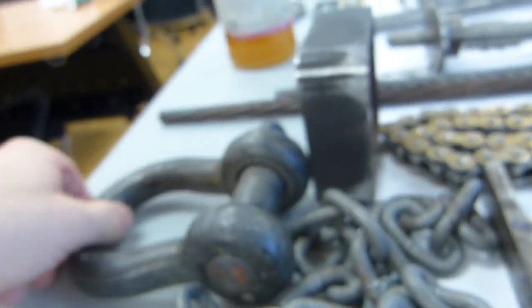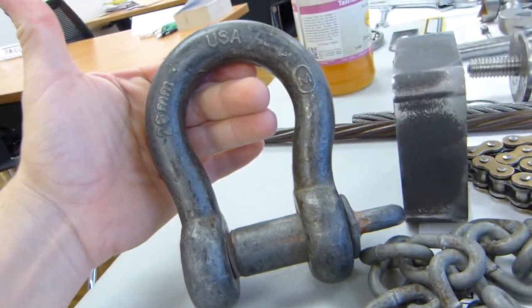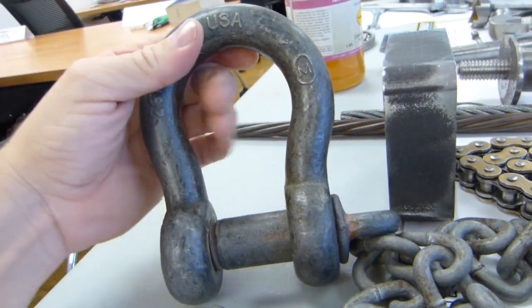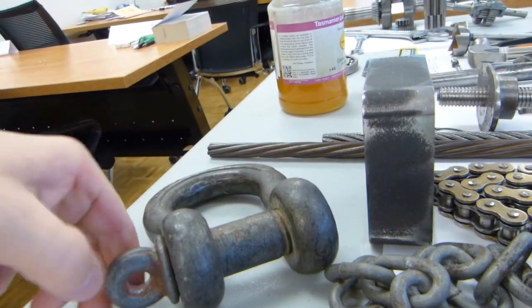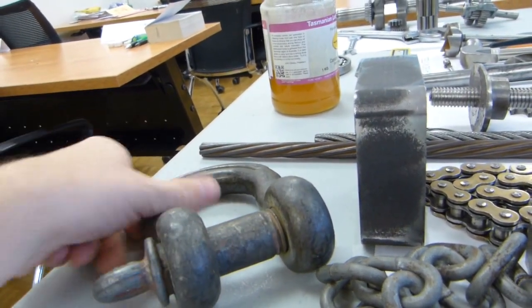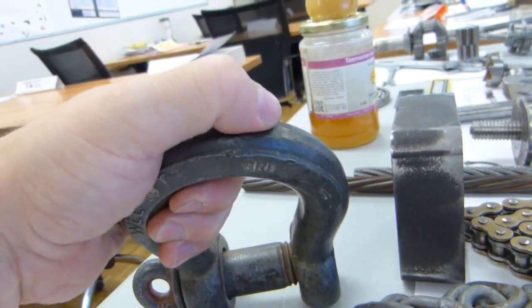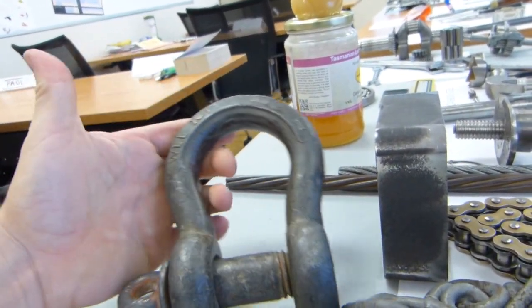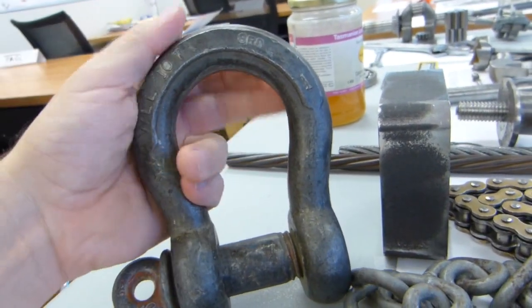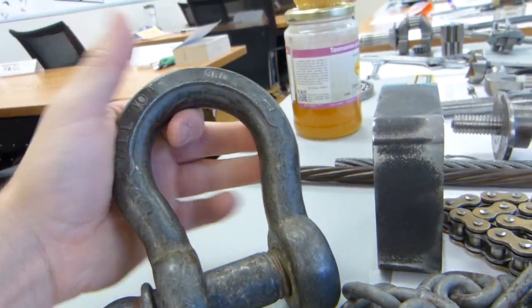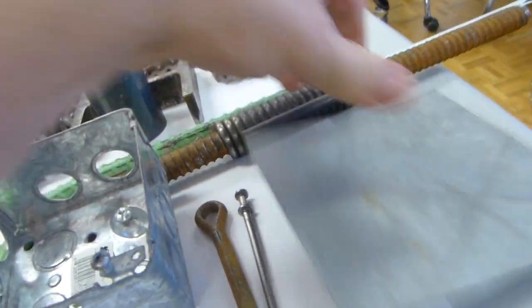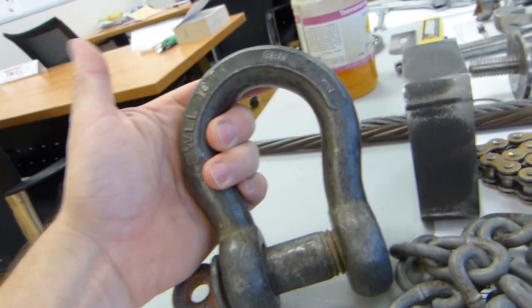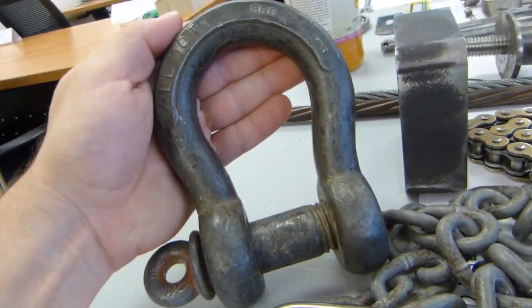The same principle applies to this item here, which is called a shackle. It's used for hoisting and rigging and lifting heavy things with chains and wire ropes and such. Again, the same idea applies. It shouldn't break and crack here on this side. And in use, it's very important that it should plastically deform somewhat. It should have a lot of give, and a lot of flexing and bending before this product fails.